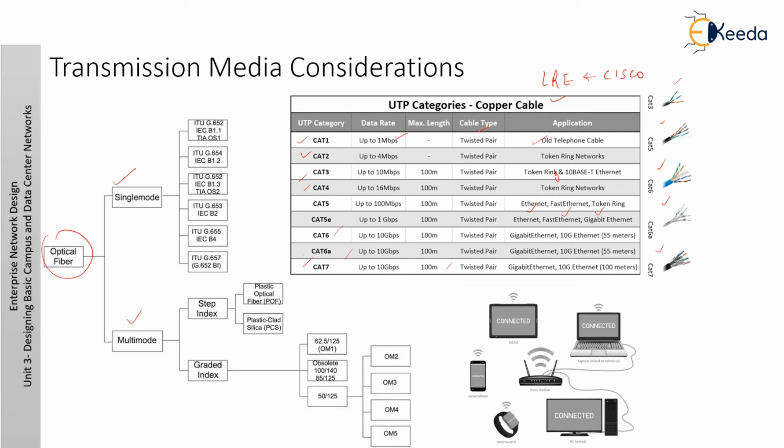Different types of optical cables exist. The two main types are multimode and single mode. Multimode fiber is optical fiber that carries multiple light waves or modes concurrently, each at a slightly different reflection angle within the optical fiber core. Because modes tend to disperse over longer lengths, called modal dispersion, multimode fiber transmission is used for relatively short distances. Typically, LEDs are used with multimode fiber, and the typical diameter of multimode fiber is 50 or 62.5 micrometers.